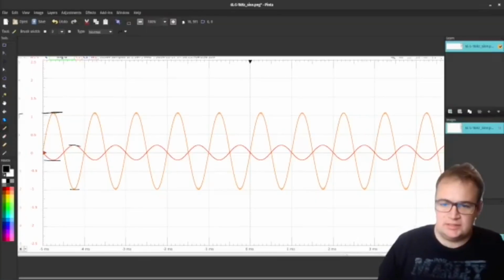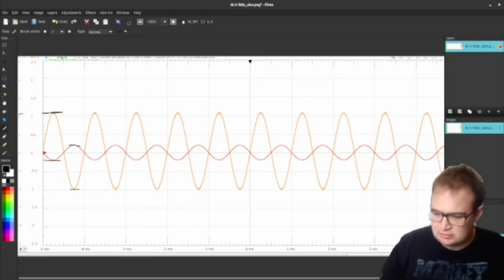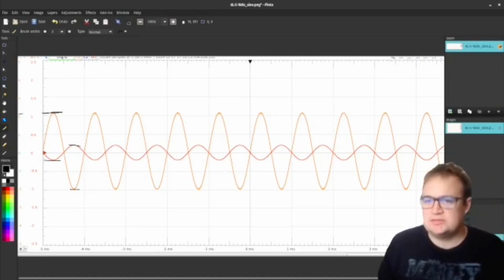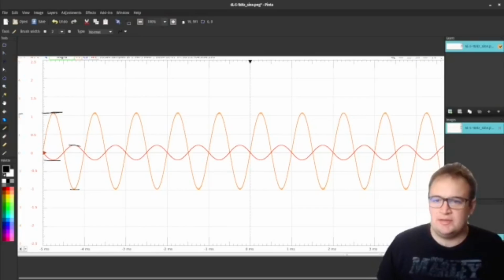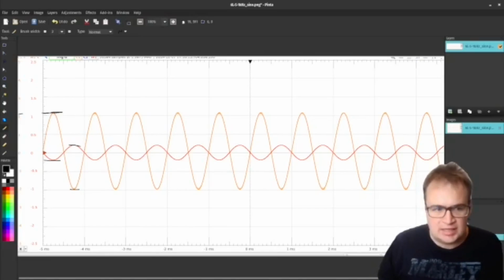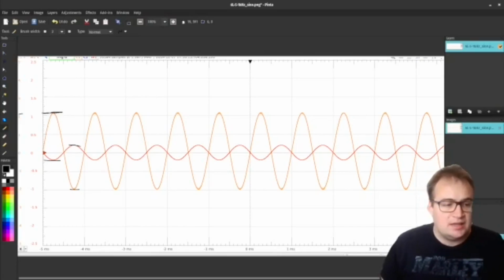Hello. So I just made a note and left it, and I still am not sure how I'm supposed to measure the input impedance. But I'm guessing I would measure the gain, and the gain would be slightly different than expected, and then I could correlate the input impedance based on how much the gain is off from my expectations.